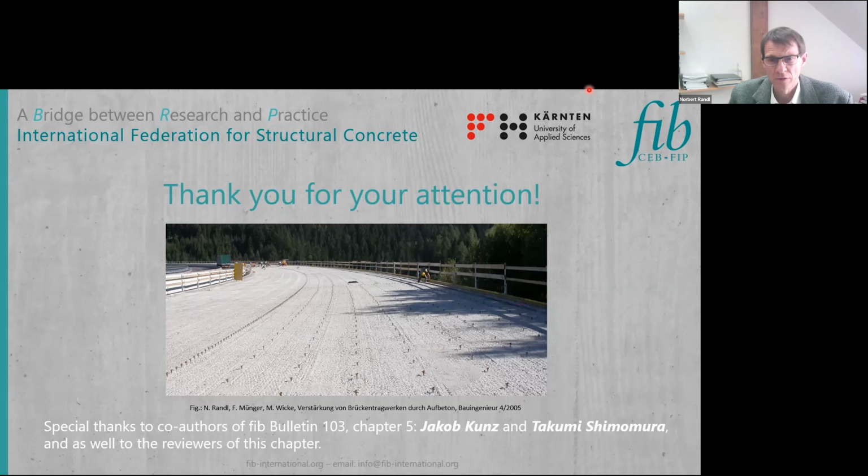So for sure, a first assessment and test to be done in advance is to check the quality and the deterioration grade of the existing concrete. Especially the surface has to be investigated. And before doing the casting, you should wet the concrete, but you should not have standing water on the surface. This is neither good.